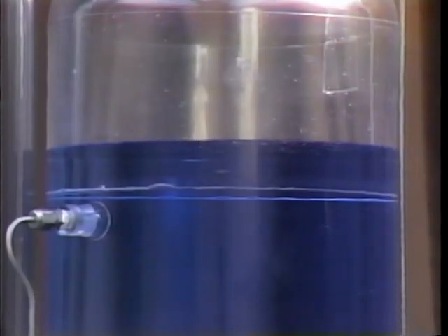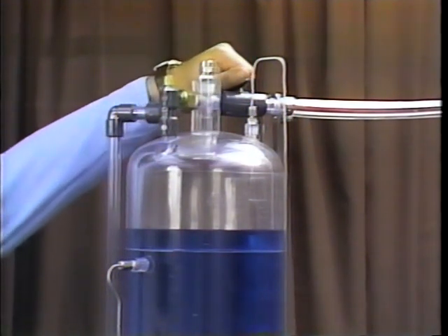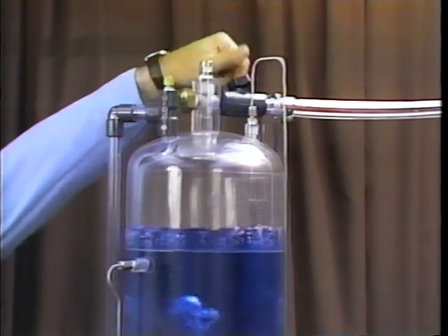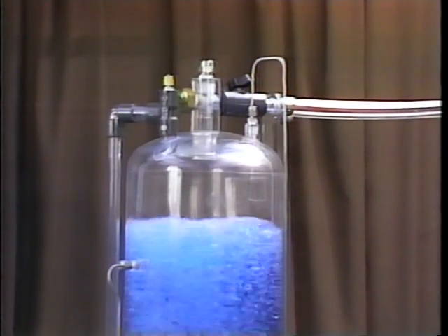Now notice what happens if we duplicate the same venting situation on a vertical tank. The liquid in the upper portion of the tank presses down on the liquid below and subcools it. When the pressure above the saturated liquid at the top of the tank is reduced, the boiling and flashing is much more violent as the liquid tries to cool itself to the now lower vapor pressure condition.